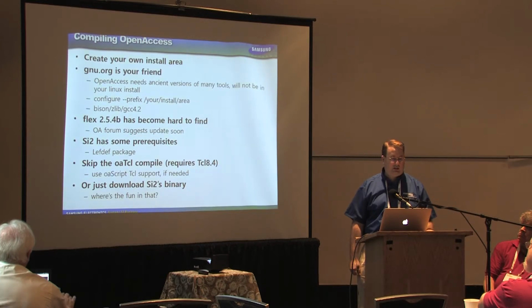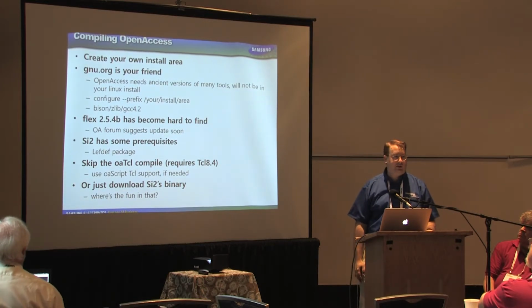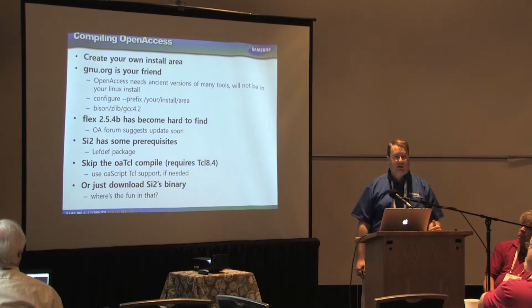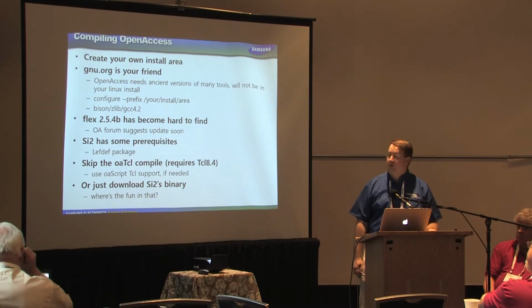Si2 on their site has a leftdef package. You have to go find that, search it out on the Si2 site, build that, merge them together, and that's also part of it. And there's a document with open access that goes through all the setting up of these and what versions are required.